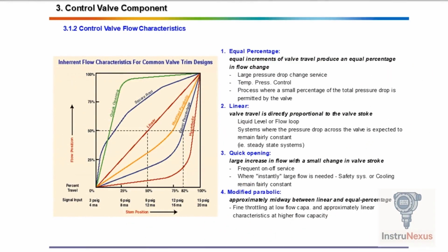3. Quick opening. A small change in valve stroke results in a large increase in flow. This is perfect for frequent on-off operations, safety systems or cooling systems where instant high flow is required.